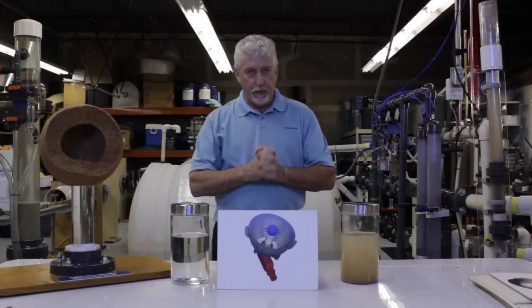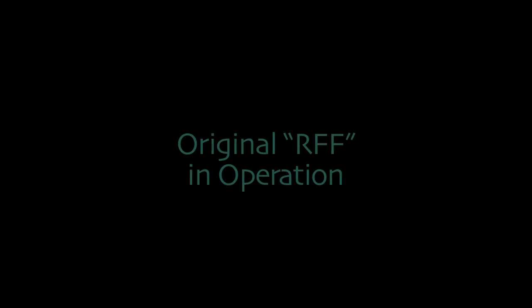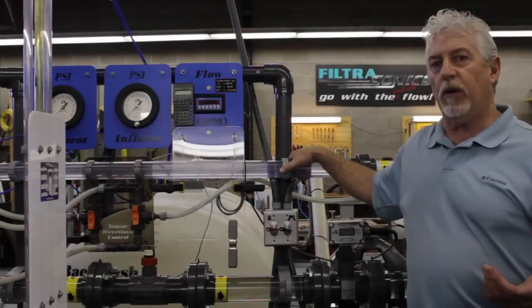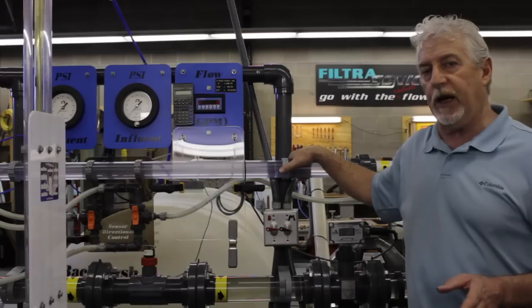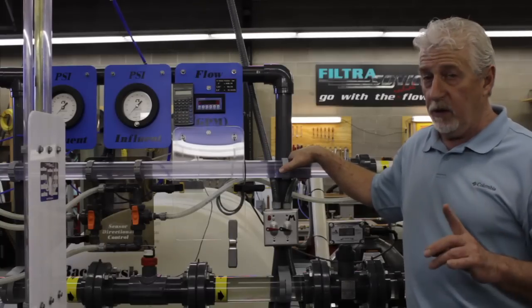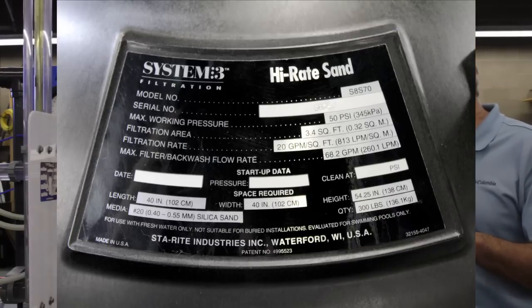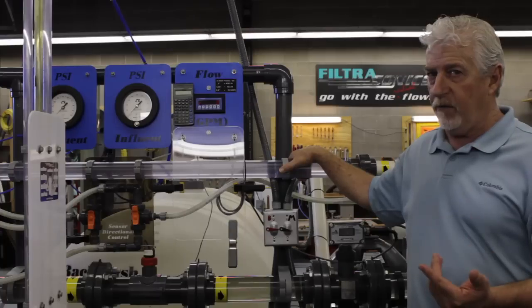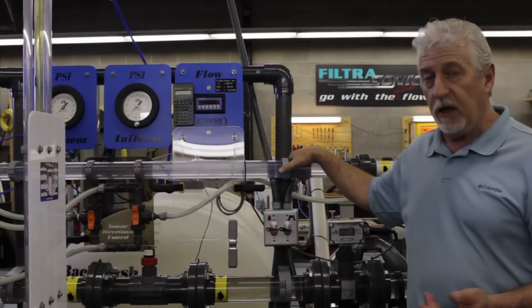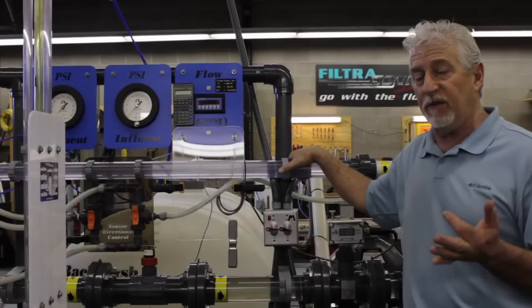Anyway, next step, I'm going to show you the radial flow filter that we've got in operation here. We built our alpha prototype radial flow filter out of a Stay-Right Industries System 3 sand filter tank, 24 inches in diameter. Now if you look at the spec sheet on the side of that filter tank, it's rated for a maximum flow rate of 68.5 gallons per minute. With the radial flow, we had to plumb it with 3-inch bulkheads, and we were able to test successfully up to 210 gallons per minute, over 3 times the flow rate.